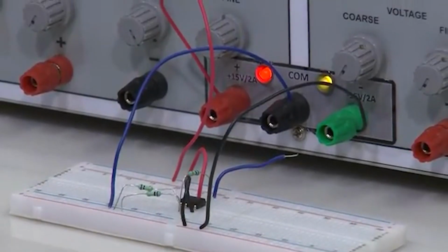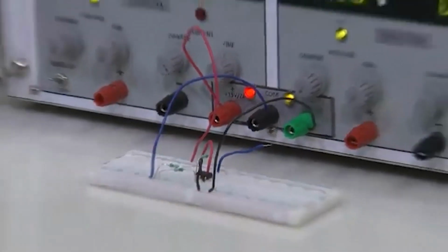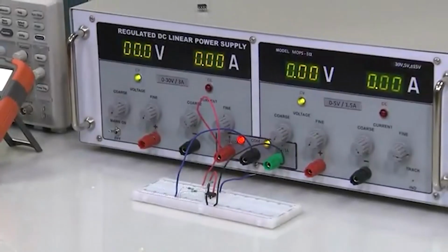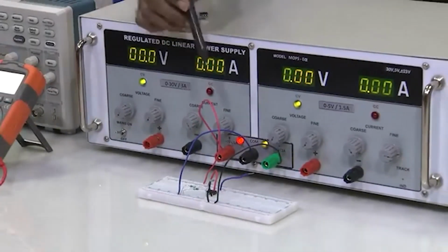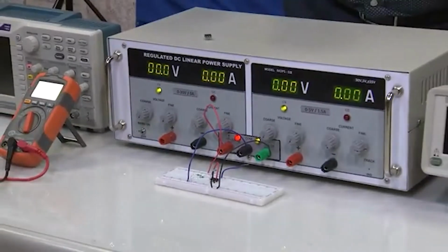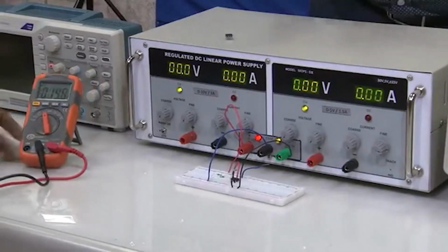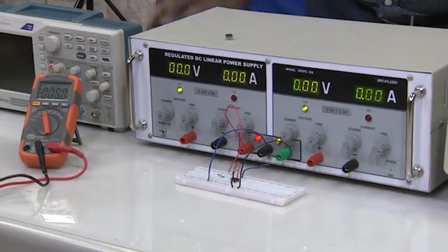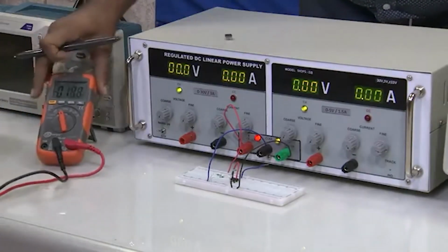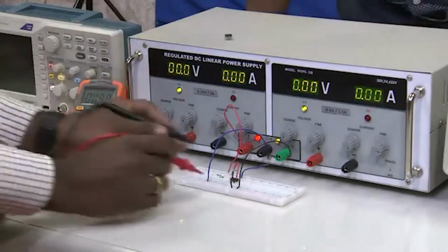Now, we are measuring the output voltage, where both the input terminals are grounded. So, now we are understanding the output voltage. From where can we measure the output voltage? We can measure the output voltage at pin number 6, or between pin number 6 and ground. So, what is the output voltage? Let us see. Again the multimeter is in DC.